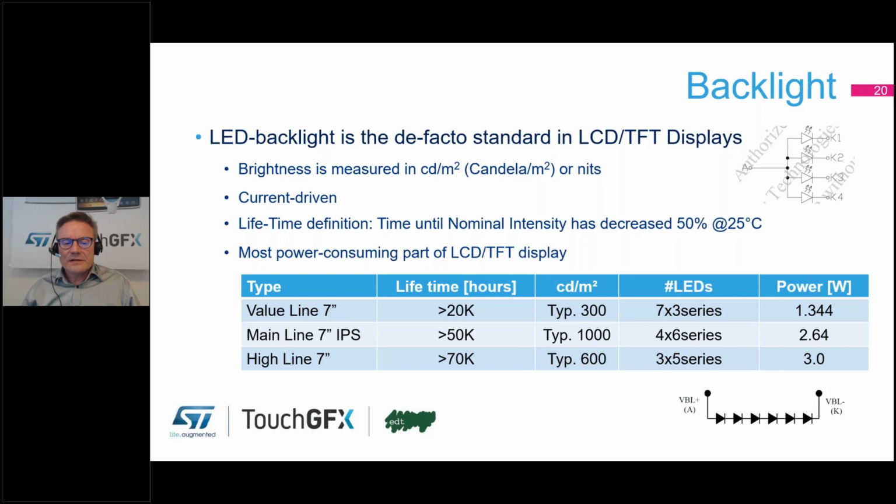I say as a rule of thumb, some 600 candela would cover your demand as a surface brightness. But again, if we don't have optical bonding, I'll come back to that point later on, you might require a display with a much brighter backlight. So later on in the seminar, we'll show you a little bit more what this is about. But as a general rule, we should cover it.